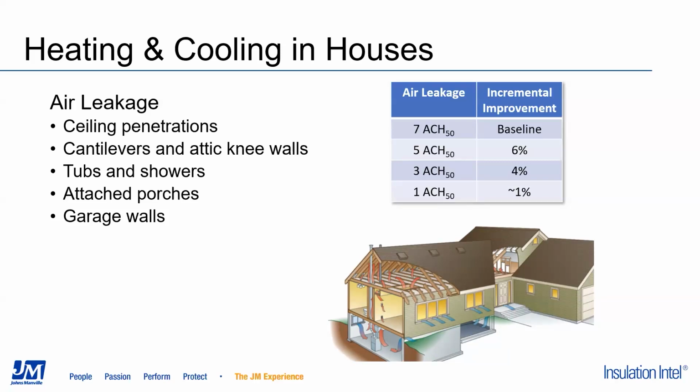Things like cantilevers and attic knee walls, tubs and showers, attached porches, these all create a bunch of large, potentially really large holes in our walls that, again, need to be blocked off, need to be sealed. The best opportunity to do that is when the home is being built. Trying to do that after the fact is much more difficult.